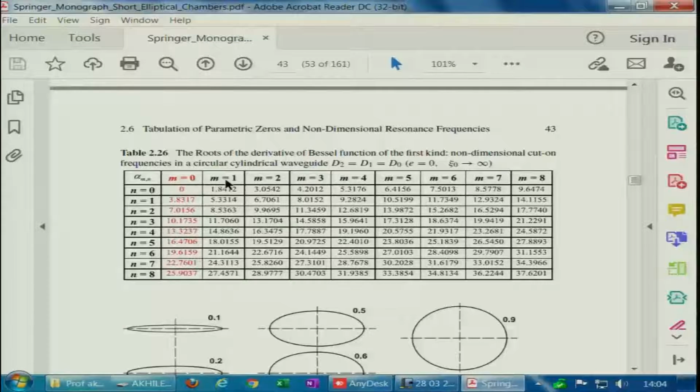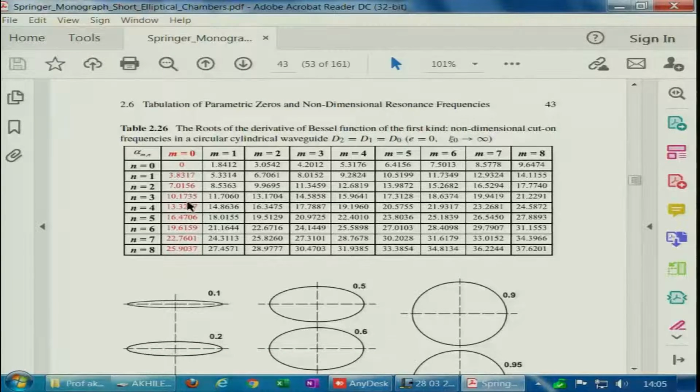For m equal to 1, 2, 3, 4 and n being 0, these are circumferential modes, but we will be considering only m equal to 0, n equal to 0, that is the planar wave mode, for which the argument of the Bessel function of order 0 is 0, and then you just have unity. So this is a plane wave mode and it comes out nicely mathematically. This is the first radial mode, second radial mode, third radial mode and so on. These are the radial modes and that is what we will be dealing with.